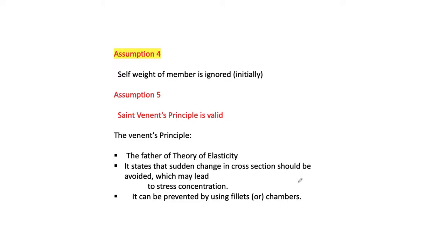Assumption 4, self-weight of member is ignored initially. Assumption 5, Saint Venant's principle is valid. Saint Venant's principle states that sudden change in the cross section should be avoided, which may lead to stress concentration. It's nothing but sudden change when you apply the load in the cross section. The stress concentration we get should be prevented by fillets or chamfers.